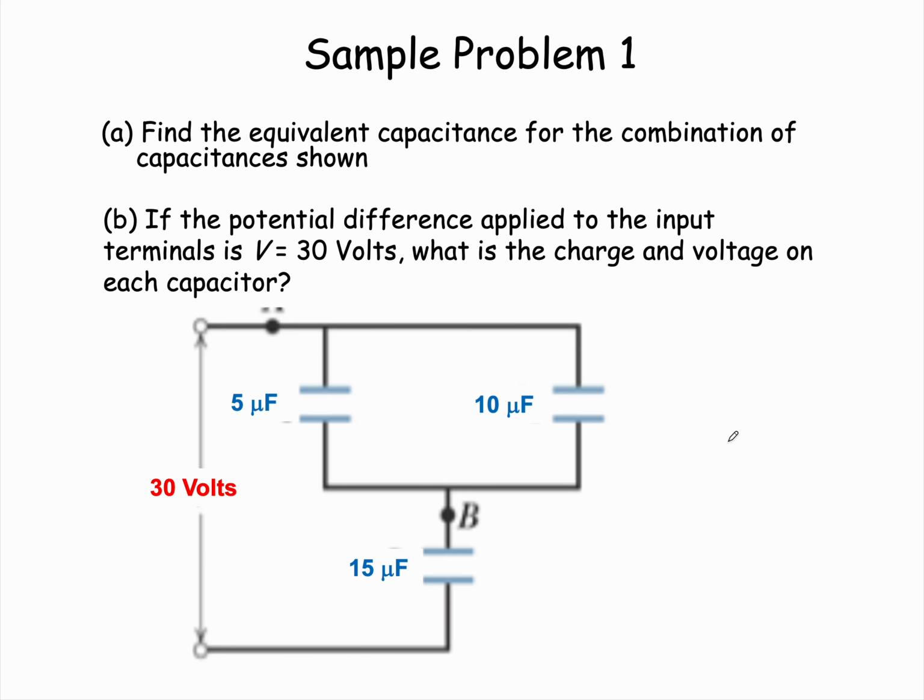These next 2 and the last 2 slides I want to do are slightly more complex ones. Are these capacitors in series or parallel? The answer is yes, they are. In fact, these top 2 are side by side. The 5 microfarad on top and the 10 microfarad are in parallel with each other. And then those 2 are in series with this 15. Their ends are connected to the other end of this one, which then goes on to the battery or voltage.